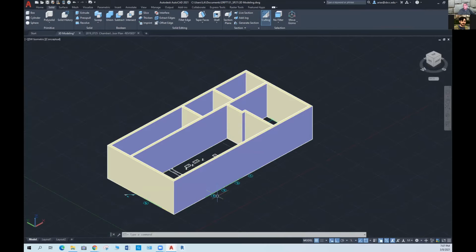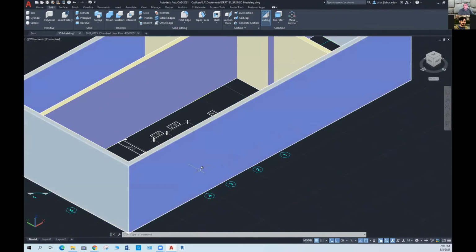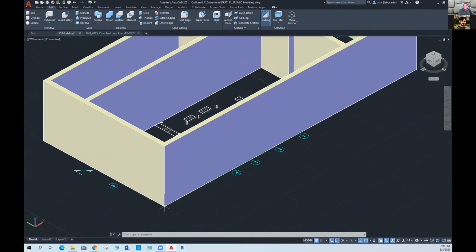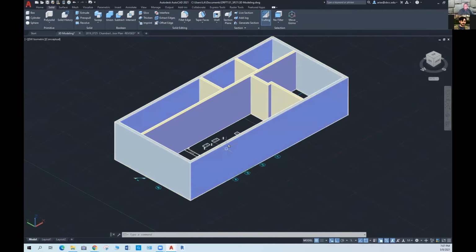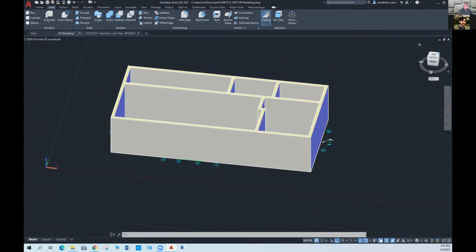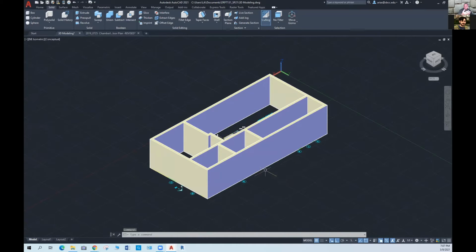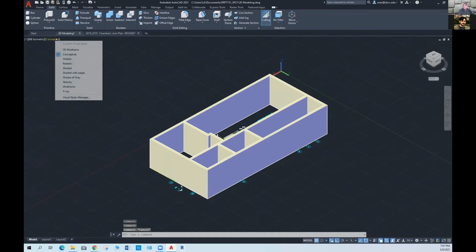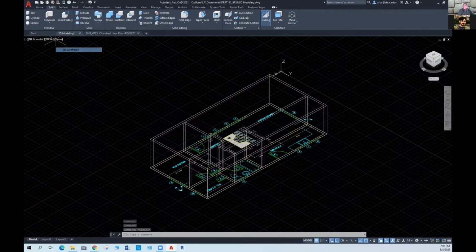The doors and windows on the exterior are easy to do because I could bring my elevation and paste it on this side, right? One side elevation, paste the other elevation here, paste the other elevation, and then just use press pull and so on and so forth. I could do that, or I could just create the geometry myself, right?